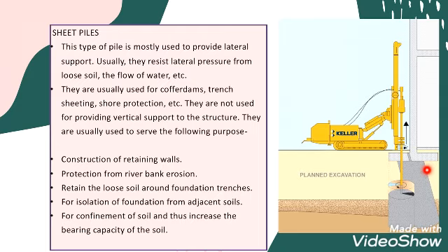They are usually used to serve the following purposes: construction of retaining walls, protection from riverbank erosion, retaining the loose soil around foundation trenches, isolation of foundation from adjacent soils, and confinement of soil, and thus increasing the bearing capacity of the soil.